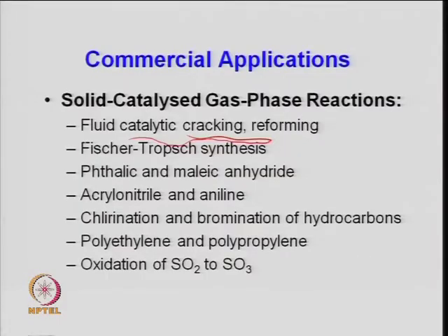Similarly, there are several other processes in the petrochemical and pharmaceutical industry where fluidized bed reactors are used, like the oxidation of sulfur dioxide to sulfur trioxide. Generally, a fixed bed system is used, but the reaction is highly exothermic. So again, a fluidized bed reactor can be a better option.